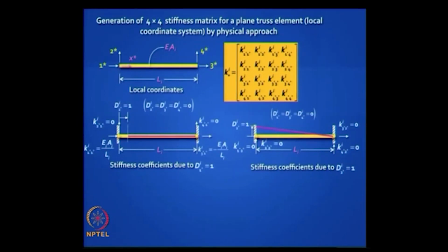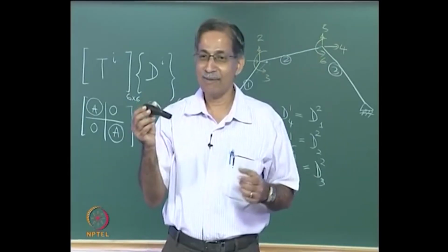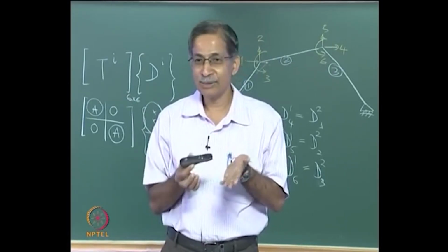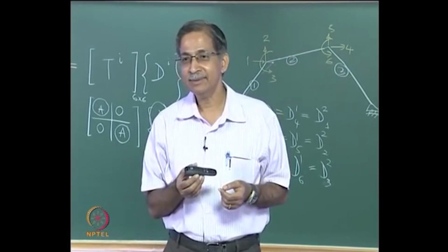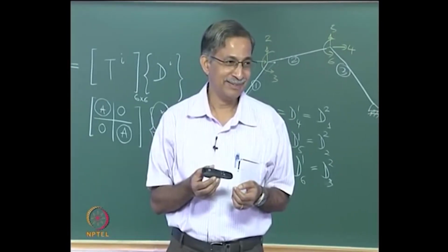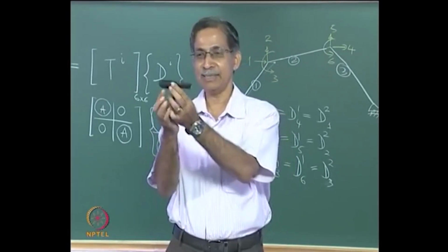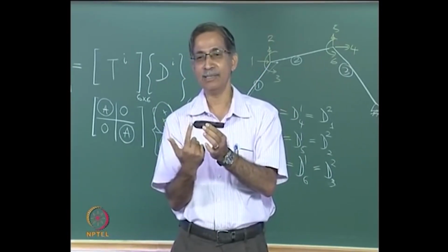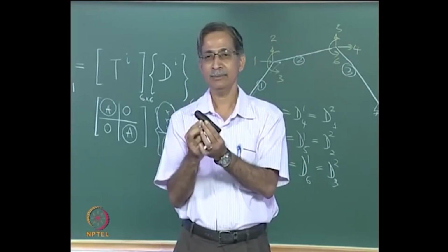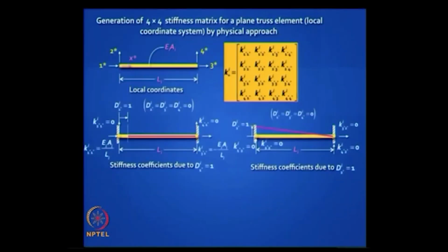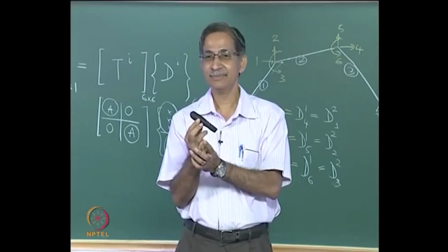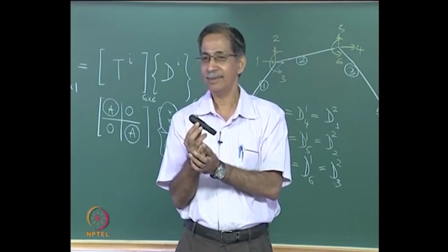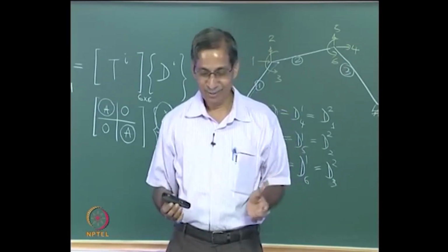See, the first thing you learnt was in a truss member you will have a force only in that member. There is no shear force. There is no shear force in a truss member. So how can you have a non-zero there? So I have a member like this. Please look carefully. I have a member like this. I want, for you this is left hand, right? I want this to go up. Okay. No problem. Right? This is rigid body motion. Got it? So this is something new.